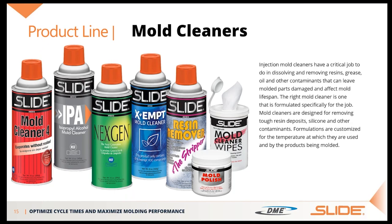You've got all this nasty carbon buildup, outgassing, plate out. What you do is you spray it on the hot mold and you run a couple shots and it draws off that buildup. So in an 8-hour shift, a customer might use it however often they need to keep going and having their parts coming out with no problems or issues. It actually works best on a hot mold, not as well on something cold. So it's a pretty cool product. It's very, very heavy duty.